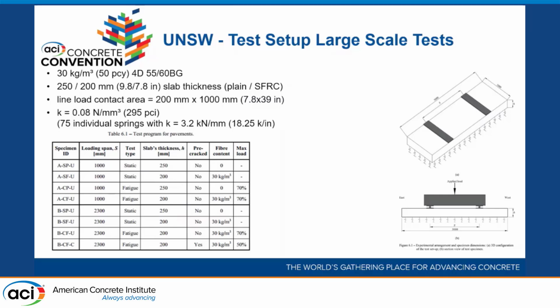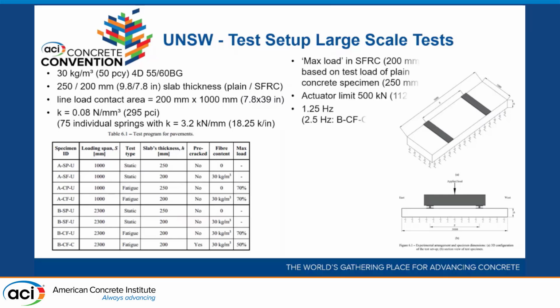This was done specifically to verify and provide justification for the round determinant panel tests. These are the parameters that we tested here, trying to mimic at least something realistic as far as the slab is concerned. Now, keep in mind, this is specifically for slabs on grade. It's for no seismic loading. It's for wheel loads, no uplift loads. It's not for slabs on piles. It's just for uniformly supported slabs on grade under the action of wheel loads.